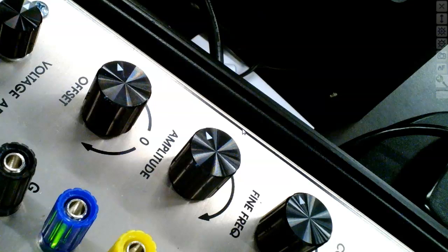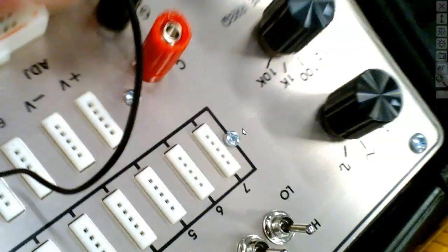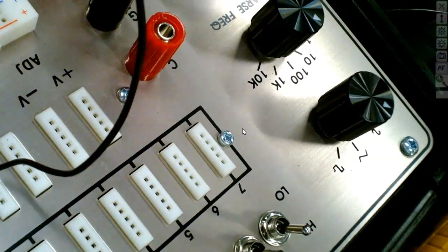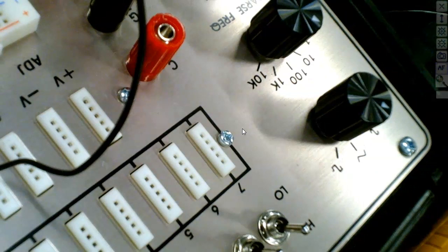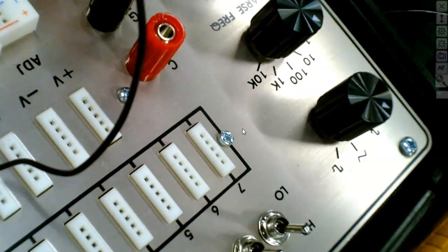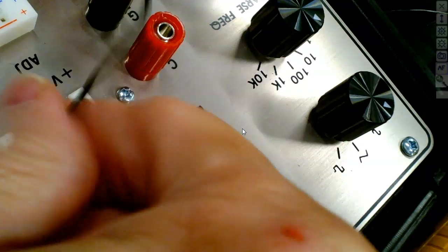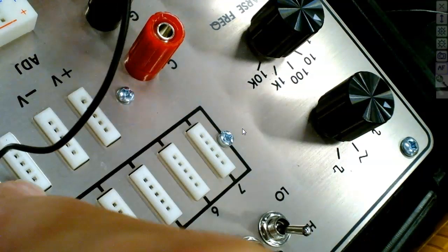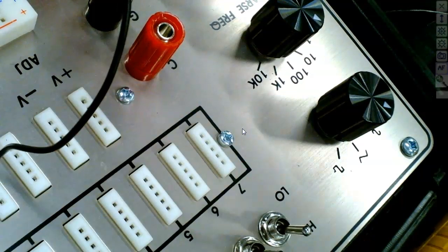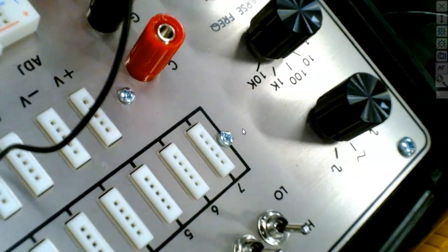You understand? What happened was I was using this over here, and this right here is the transformer; the secondary of the transformer is not referenced to that. Which is the 0 and 6.3. So I had to reference it to the 0 between the 6.3. And now everything works.